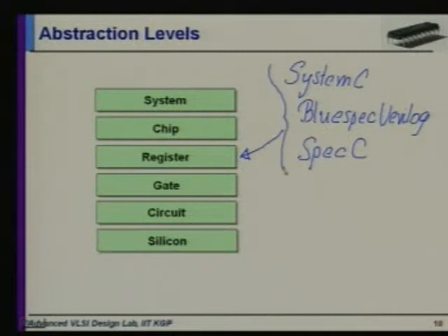But so far they are mainly modeling languages, used for modeling the design at the system and chip level, making sure that whatever you intend to design is correct. From there, you pass an English document to the designer, and the designer uses that to start coding the register transfer level version of the circuit.